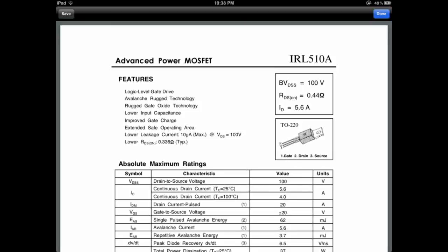You could get crazy if you wanted it to not have hardly any leakage, gate to source, and put like a mega ohm in there or something. But a lot of times if you do that, you may start seeing some slewing, but then again, you may not care. So just play with it, experiment with it, put a scope on it, see what it looks like turning on and off, and see what you can play with. So main thing is have fun with it all, guys.